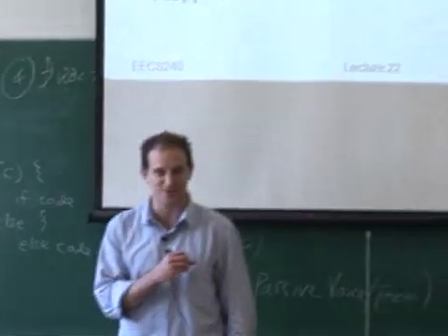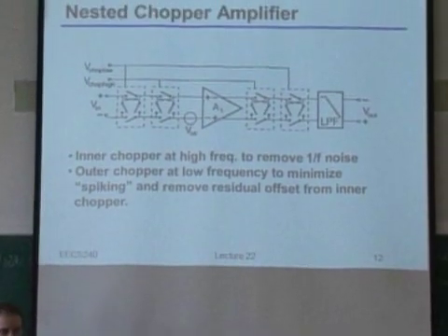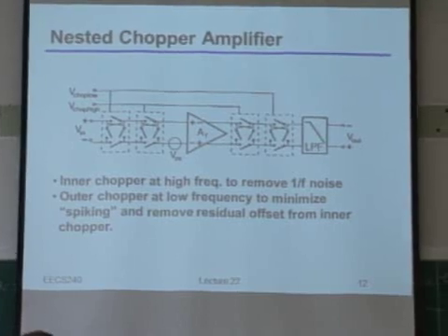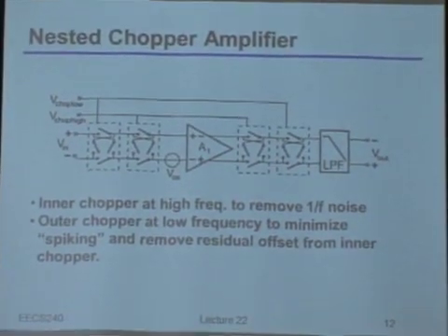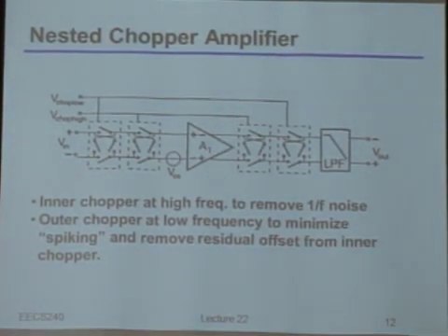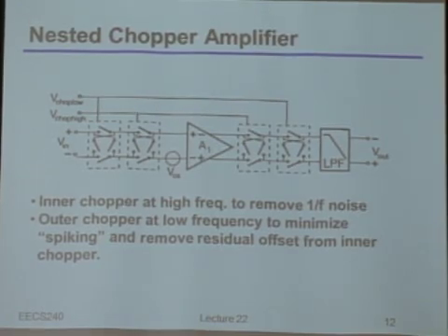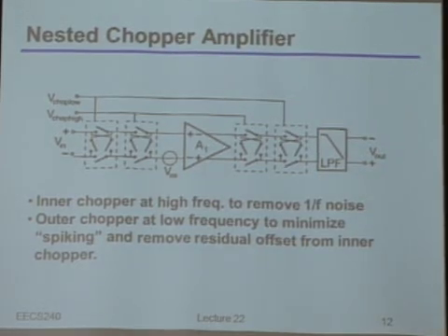Okay, so we were talking last time about offset cancellation, and we talked about the first general category, both correlated double sampling, and then we finished up with this chopper stabilization or chopper type of amplifier design. So unless there are any questions on that, I want to move on and talk about the second general category, which is essentially figuring out how to inject a DC signal to cancel that offset. So before I do that, any questions?